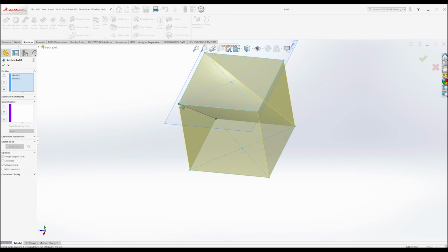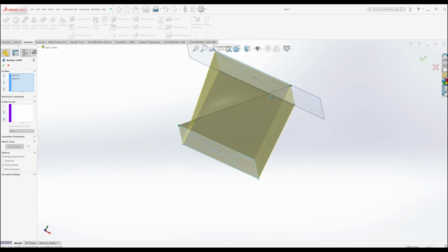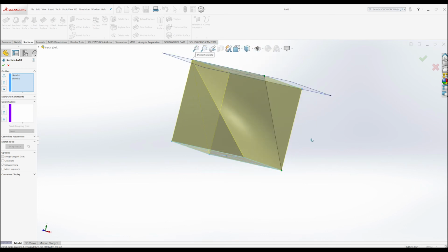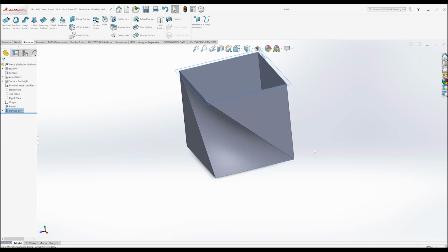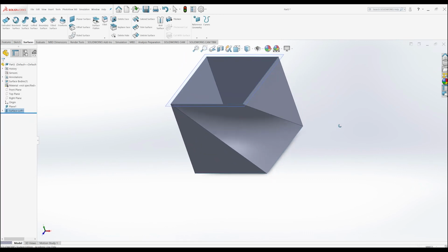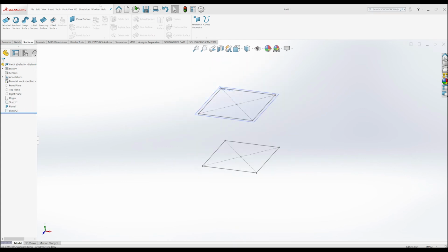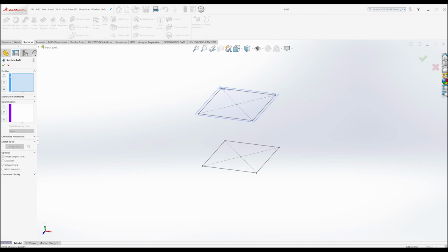So you can move these around to create those different curved shapes. Now you'll notice that my one doesn't actually have a curve going all the way around, it's just got this slight slant curve here, and that's just because of the way that the surface loft has been created. So we can delete that one, and then we're going to go back and start creating using our lofted surfaces again.